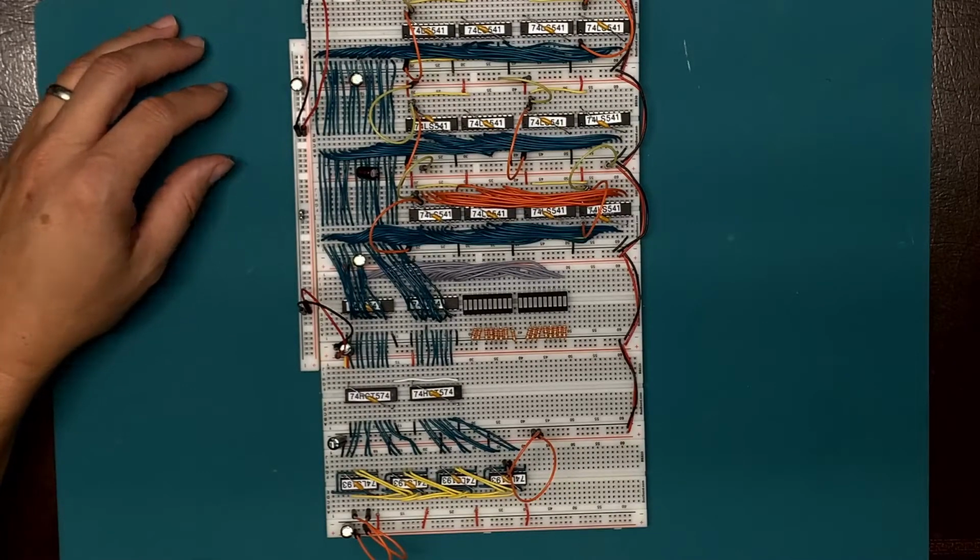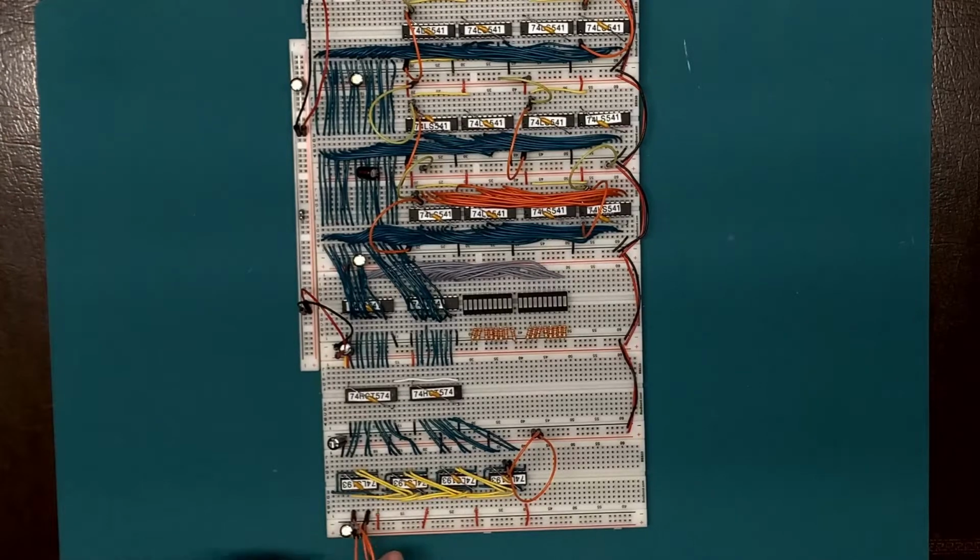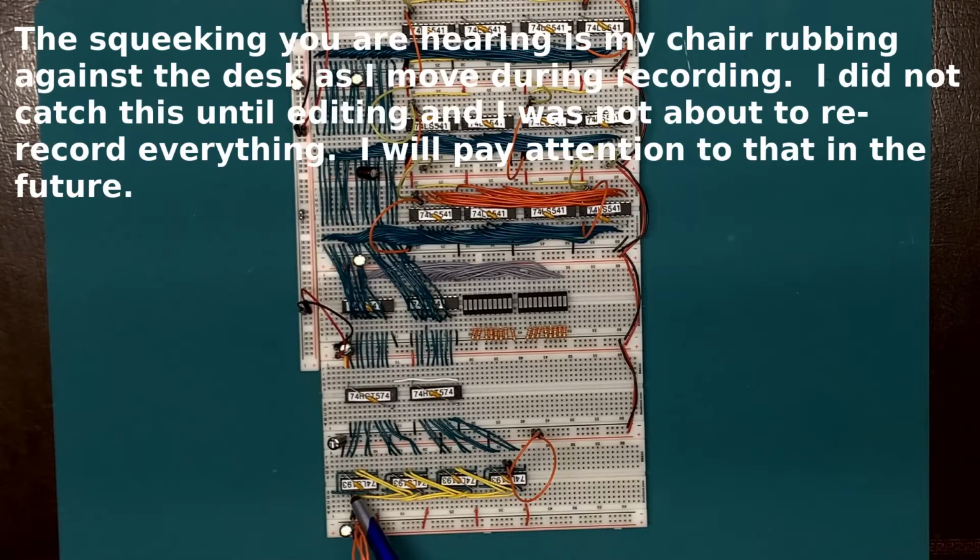Okay, now that that's done, a couple of things about the wire up. First, I decided to go from most significant to least significant as I did the wire up. What I ended up doing is extending the inputs over here, and it's difficult to see on this end, but 0, 1, 3, and then 2. Yeah, the last 2 bits, the most significant bits, are out of order there. And the least significant bit is on the left-hand side rather than the right-hand side.